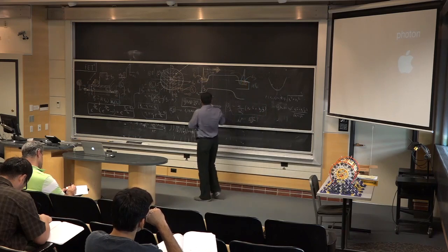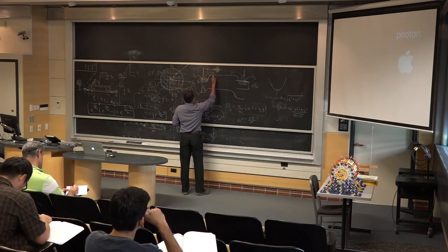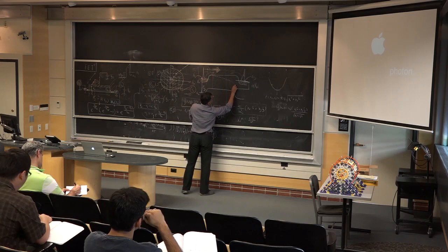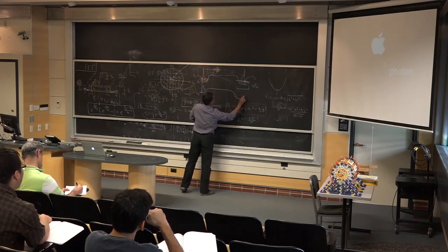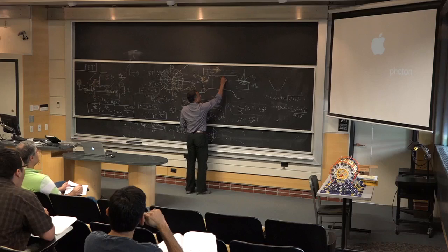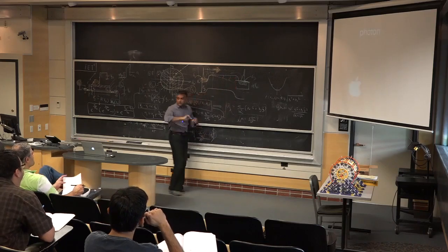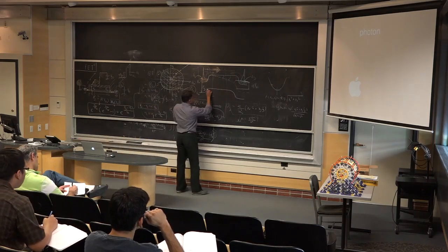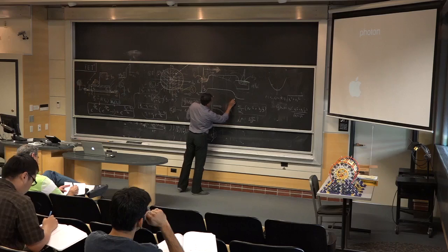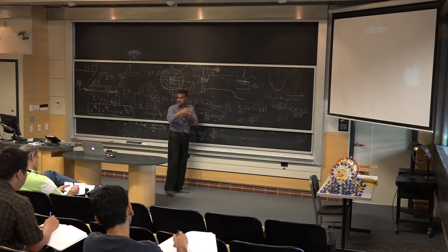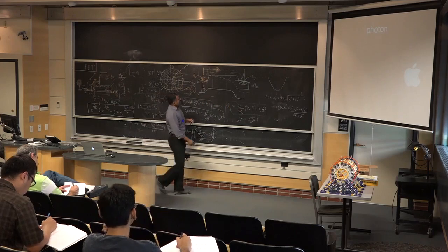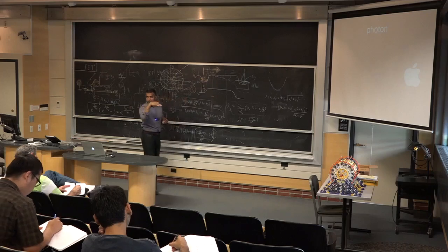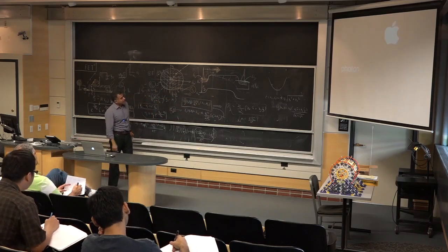So what will happen is the bands have to bend, and let me sketch it now. The bands now have to bend down, and then go down gracefully till here. So the band that was here has to bend like that. If the conduction band bends like that, the valence band has to just follow. The band gap is not changing just because you applied a drain voltage. The band gap just follows. So the valence band also bends. And now you can even classically see that an electron would like to move this way, right? Again, from our earlier pictures, it's going from the source to drain.